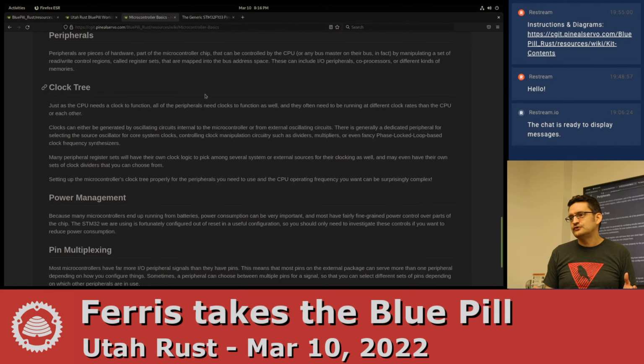It's a 32-bit address space. That means it's 4 gigabytes large. And we've already said that we've got like 20K of SRAM, and we've got either 64 or 128K of flash. So what's in the rest of the 4 gigs? Well, mostly nothing. But there are some important regions that have the control registers for these peripherals mapped into them.